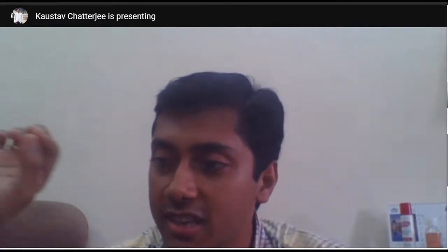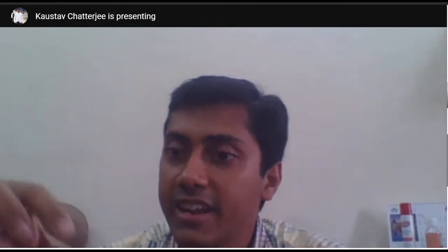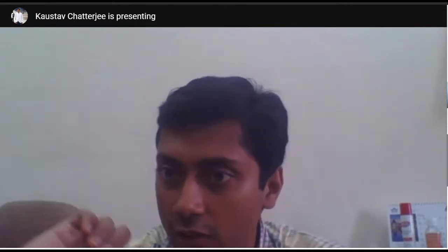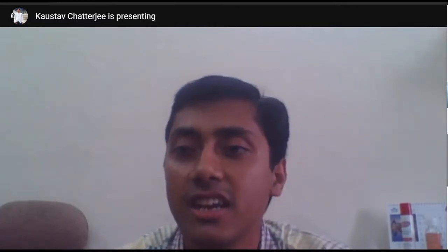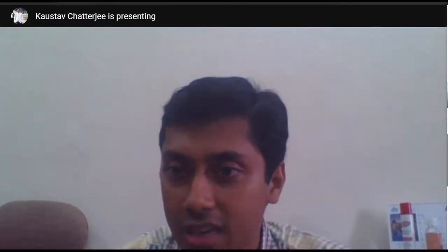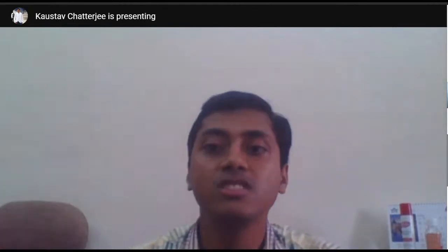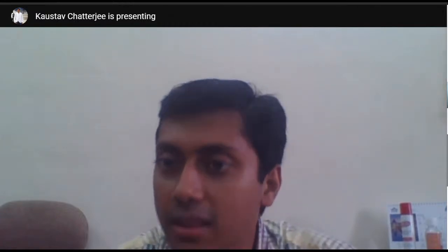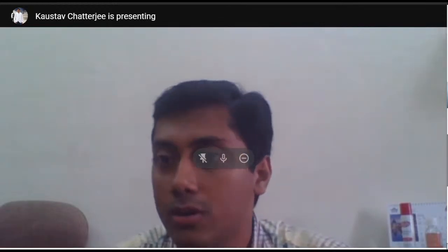So it depends upon the condition and the problem we are analyzing. For clay, in that caisson foundation, if you see the layered soil we have, the second layer, the sandwiched layer, is a saturated clay model. So for that, I have taken Cam clay. Obviously, because I have also modeled the flow of water through the porous medium, I have taken that into account. So basically, depending upon the problem that you are modeling, the constitutive model accordingly has to be guided.